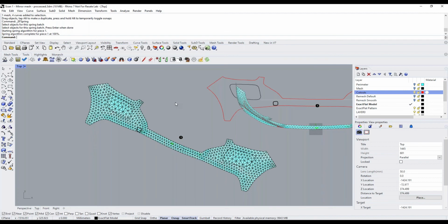Well, it depends on the type of edits that you're talking about, Chris. First of all, we can produce a DXF output, and a DXF output is a layered file made for cutting tables or plotters, or we can produce a PDF. Both outputs are available to you. You can then either plot your output files on paper and cut them out with a paper template, or if you have a cutter or you're going to send it out to a cutting service, you can send the DXF itself out to be cut on an automated cutting table. Either option is available to you.